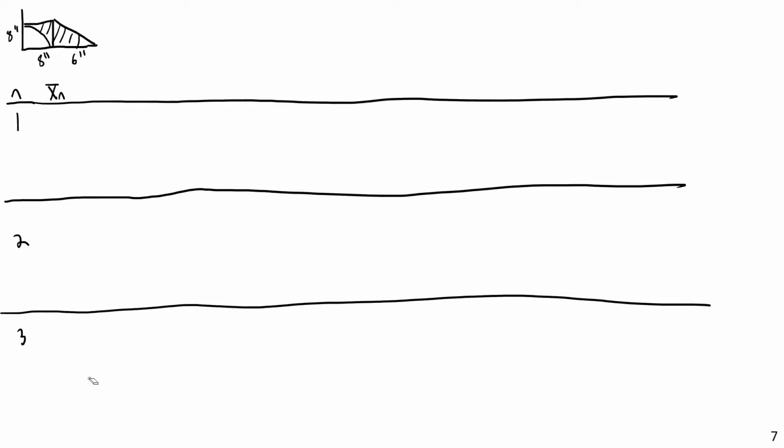I might not actually want to extend these all the way down because I still have to save room for a summation space. Because some of these columns we're going to have to sum, as we saw before. And this represents the coordinates of the centroid of each of these pieces.